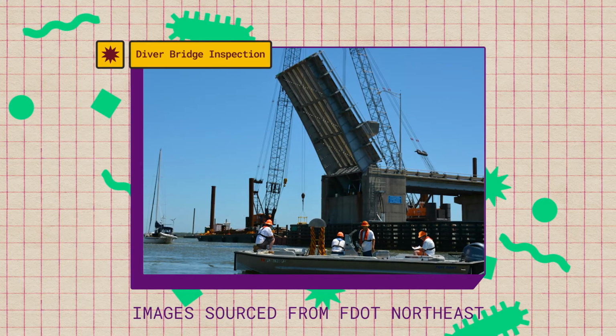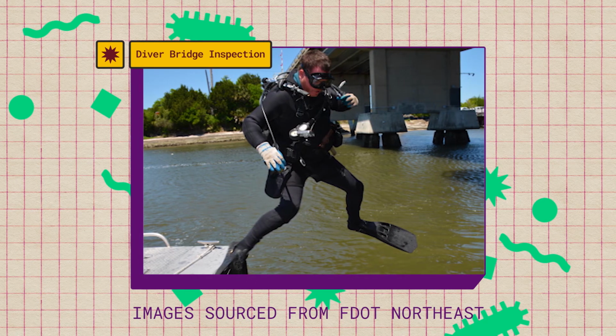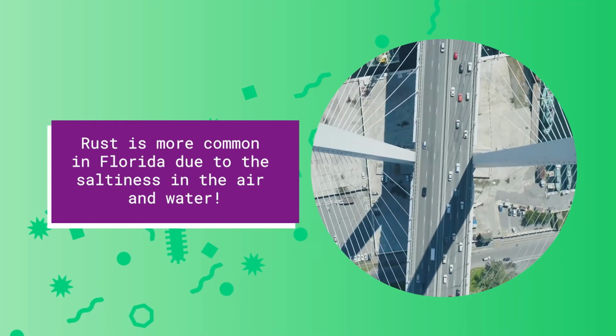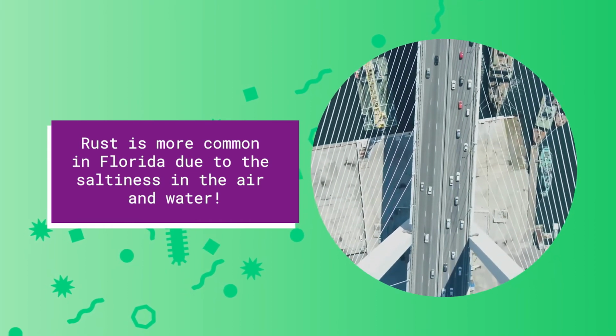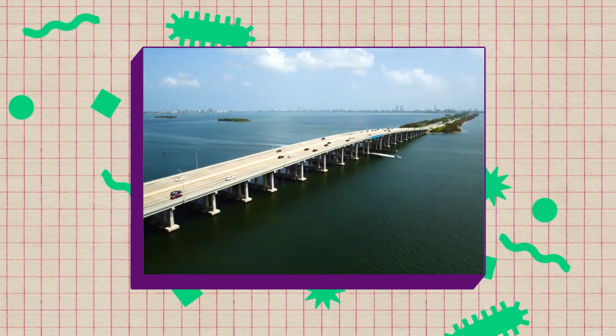In our department, we have divers because we not only inspect the top side of the superstructure of the bridge, we also inspect the foundation. We in Florida have a coastal environment, so we're very much looking for corrosion that happens due to the salt in the air and the salt in the water. And so we provide repairs for those defects or concerns to make sure that the bridges are maintained well and they're safe.